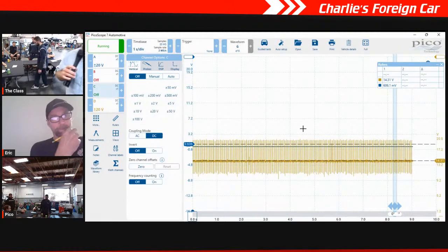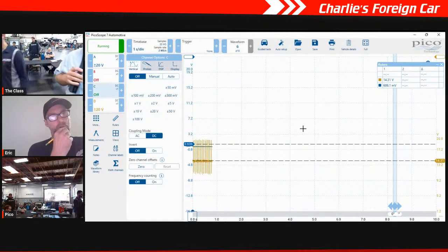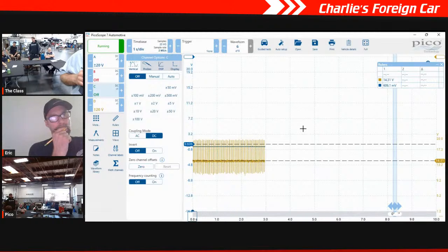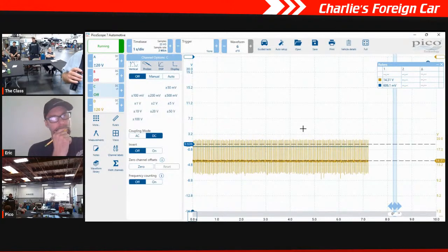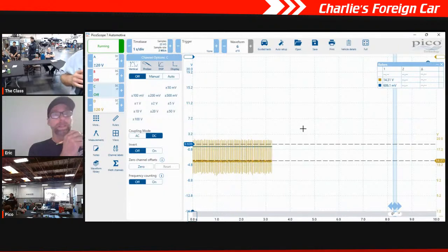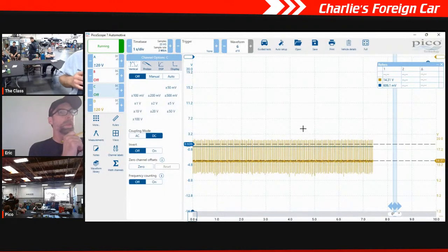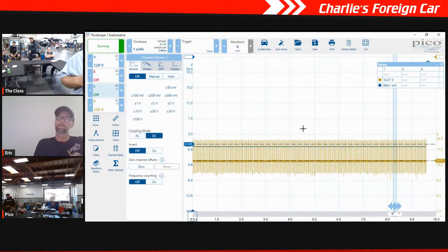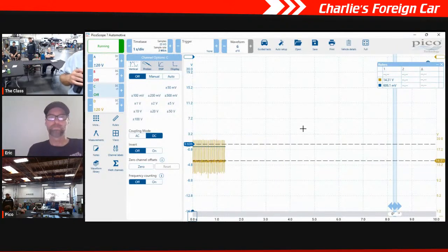It doesn't have a duty cycle like the intake has when it's idling. But when you activate it and you're watching it with a scope, it goes down to 600 millivolts, because the DME control says to go to ground. But nothing changes.